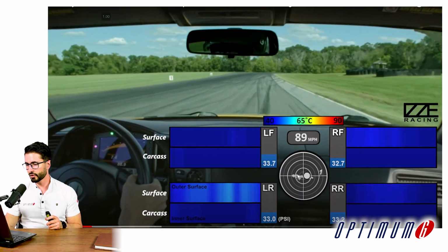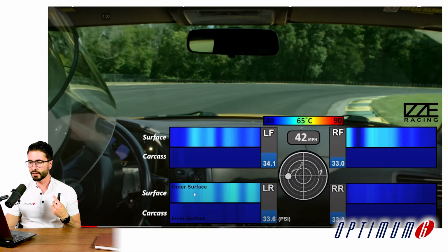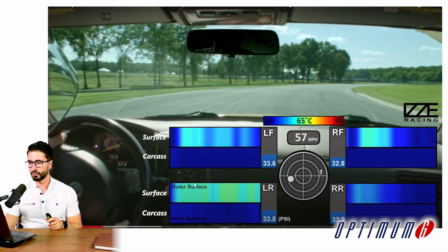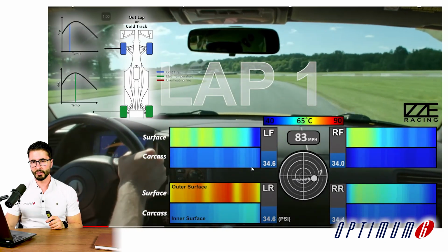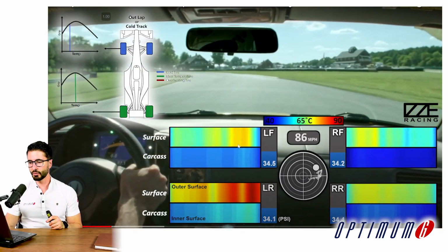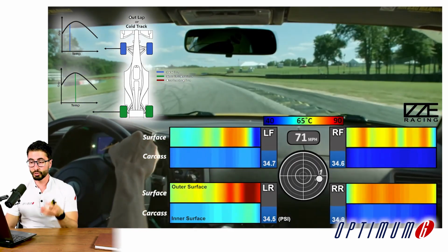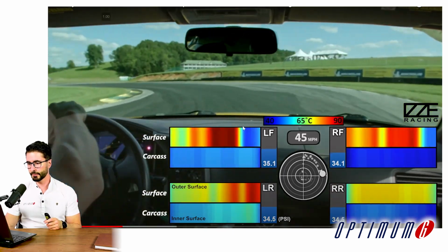Besides that, we have the pressure and accelerations. So we can see, as we mentioned, that for rear-wheel drive cars, the rear will get temperature more quickly than the front because you have traction, so you are putting energy. The driver needs to be careful in the first few laps because, as you can see, the tire is still a little cold. And if you're pushing too hard, it's gonna get graining, cold graining, because the material is more brittle, as we saw in the first episode.